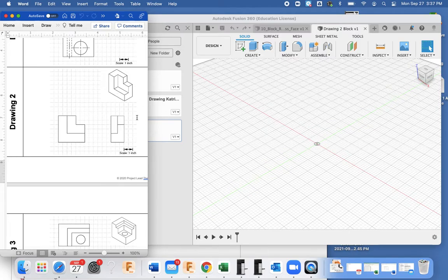Now the first thing we're going to do with this is look at the overall shape of it. It is pretty much just a rectangular block, a rectangular prism. And the overall dimensions are 3 inches tall, because every 2 blocks is an inch, by 3 inches wide by 1.5 inches deep. So I'm going to create a box that is 3 by 3 by 1.5, okay?